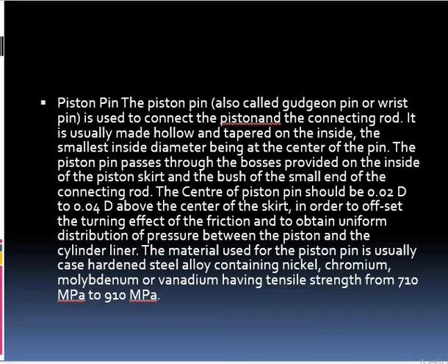This is very important. This piston pin plays a major role in transferring energy from the crankshaft to the piston. Generally, the material used to manufacture the piston pin is case hardened steel containing nickel, chromium, molybdenum, and vanadium.